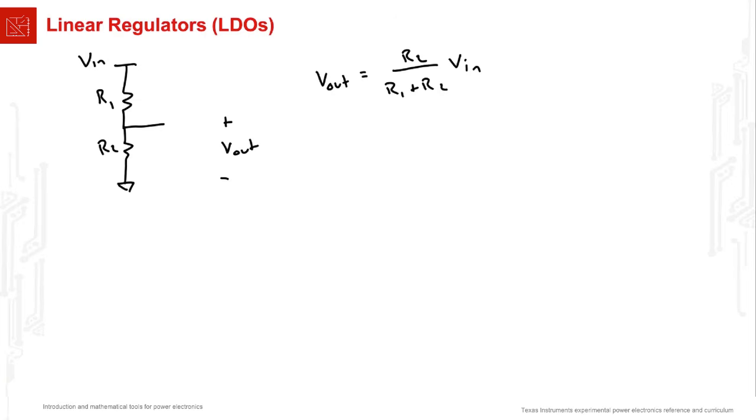The problem with doing this kind of voltage conversion in a power converter is that, kind of by definition, we want to deliver a certain amount of power to our load. So if I go ahead and draw a load in here, this load may be a current source or a resistor or some other complicated impedance. I'll just draw it as a current source though. This is my load.